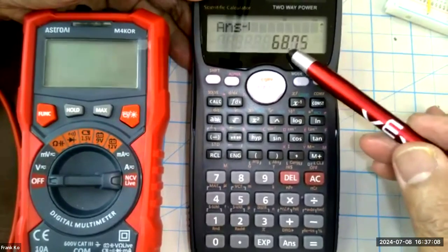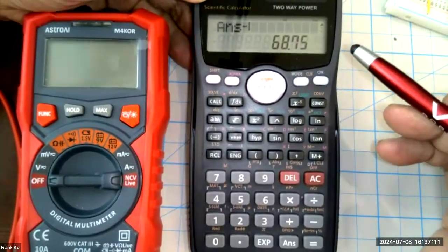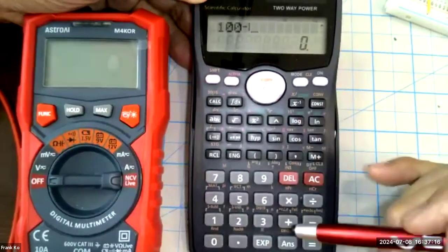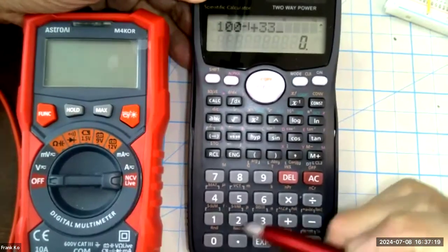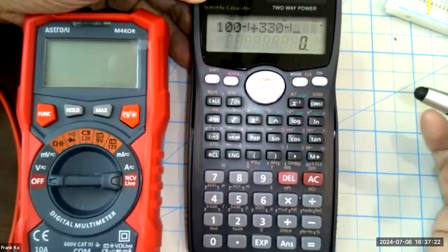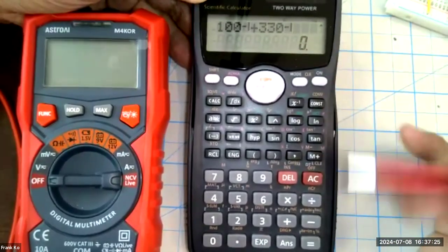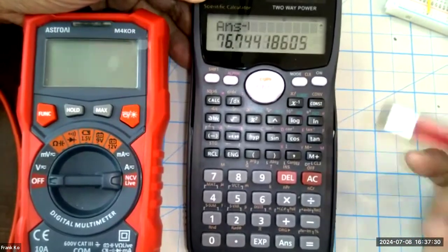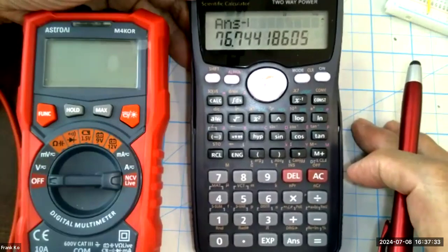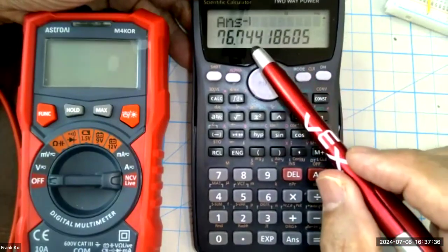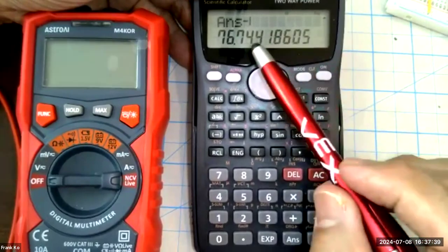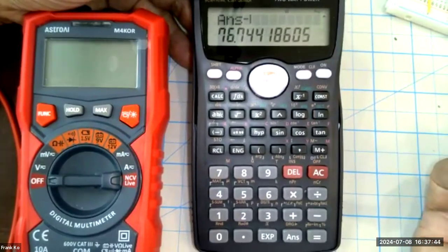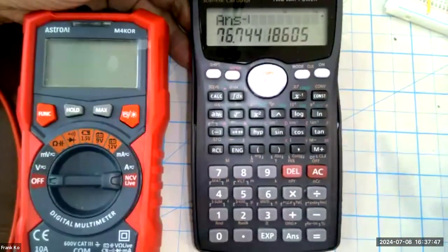You should write this down, record this into your journal, and the next calculation is R1 parallel with R3. So let's clear. R1 was 100 ohms, so 100 reciprocal, and we're going to add that to R3, which is 330 ohms. Hit the reciprocal. There's no add after this because there's only two resistors. So you hit equals, you hit reciprocal one more time and hit equals, and you calculate 76.74 ohms. Record that. Now, yes, it shows a bunch of other digits after the decimal point, but we always round to two digits after the decimal point. So 76.74 ohms is what you would calculate for R1 parallel with R3.